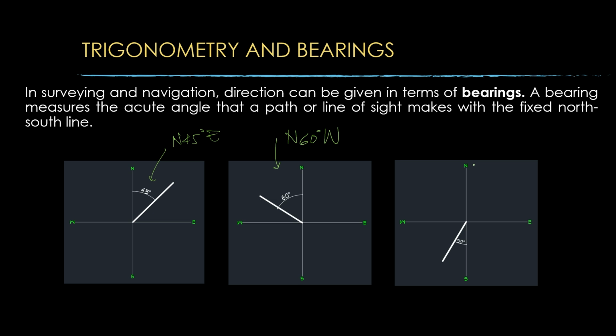And for the last one, that would be, okay, so automatic, it always starts from either north or south. So that would be 30 degrees southwest. So S 30 degrees W. Okay. Do you have any question? This will be useful in your surveying, particularly if you're computing for the area of a lot. And you can measure dimensions. Basic trigonometry is very useful.